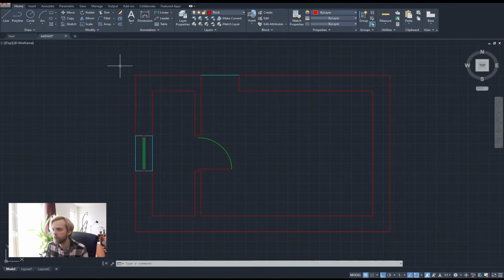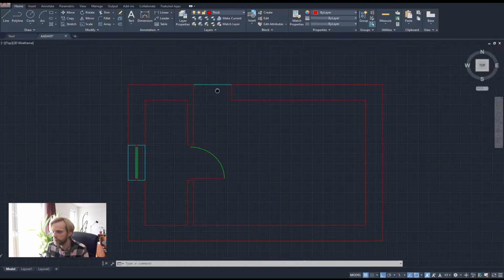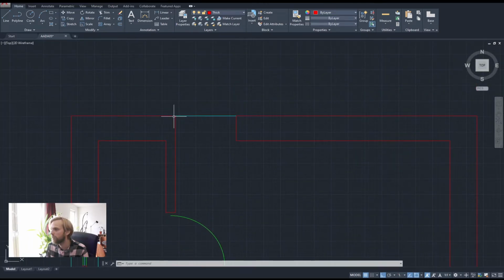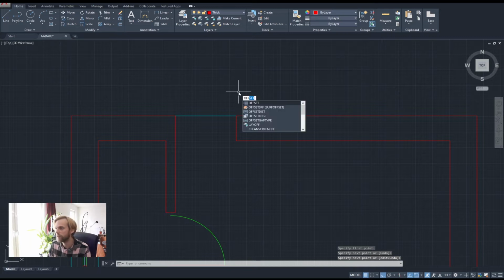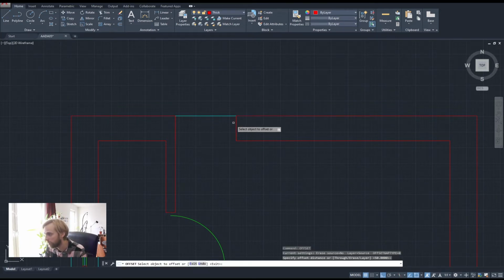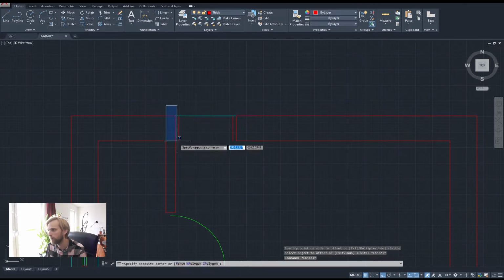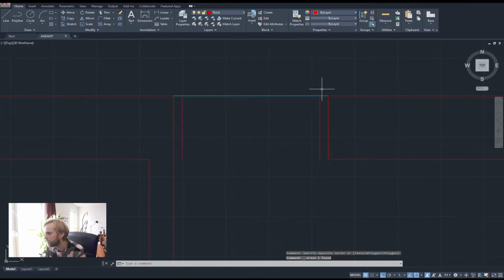I will show another method of how to create that arc in this version here, because we need a doorway here. So let me do the same thing first. From here to here, we have a line segment. From here to here, we have a line segment. I offset them 50 millimeters, offset inwards, escape out, delete the trash or the helper lines, like that. Create a line segment, bam, something like this.